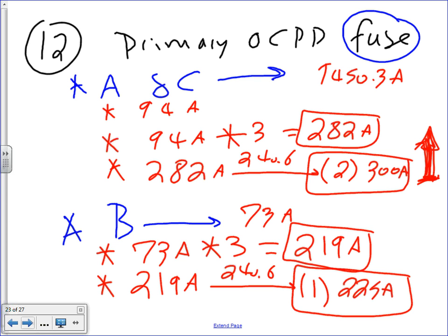From reading it, it just seems like it says we're 125%. It's like only if it's 125% on the secondary side, you go up. Otherwise, if it's not 125% on the secondary side, you go down. Yeah, because note number 1 is right next to the 125. It talks about if you multiply by 150, you're not supposed to multiply by 150. So if you multiply by 125, which it doesn't have on the top one, it doesn't say it, so you would go down. It just automatically goes up. Okay, good point.